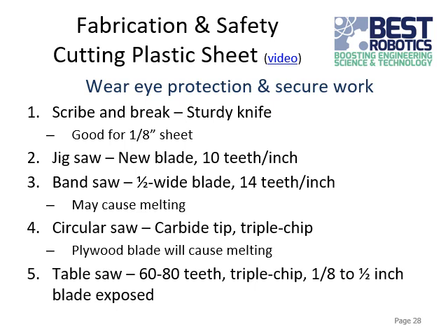You can use a bandsaw or a circular saw or a table saw. And similar sort of things for all these. I won't go into too much of the details here, but it's here for reference. Just know that with some blades, and when it's going really fast, it can actually melt the plastic as it cuts. It's not a bad thing necessarily. Just be aware of that.